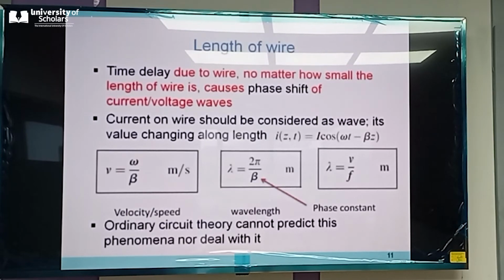What happens at very high frequencies is that the wires start acting like transmission lines, where the phase shift between the source end and the load end becomes an appreciable fraction of 360 degrees. When that happens, one has to explicitly take into account the delay between source and load.